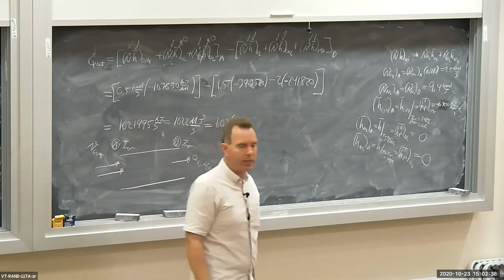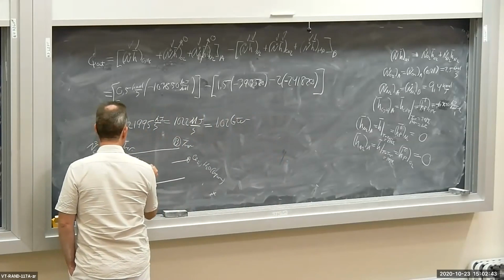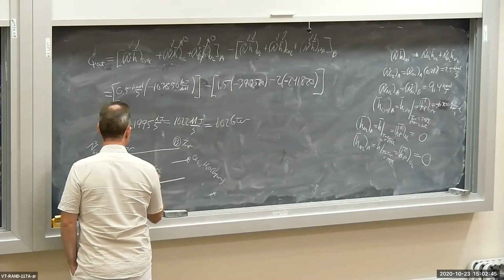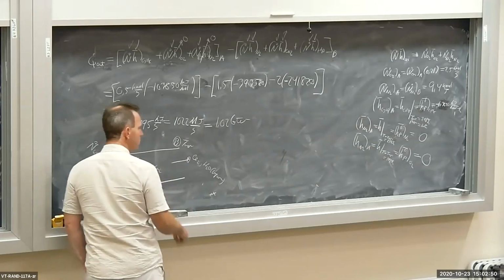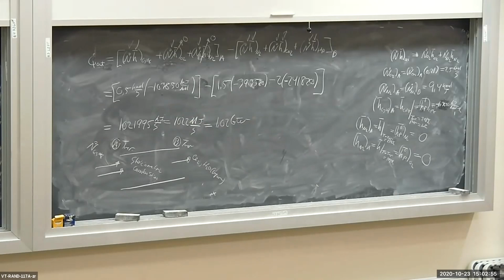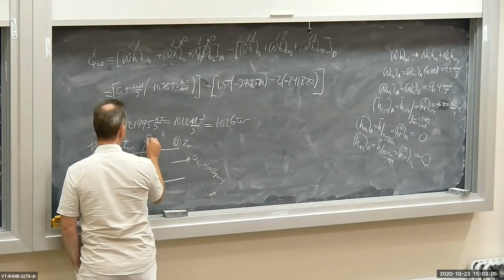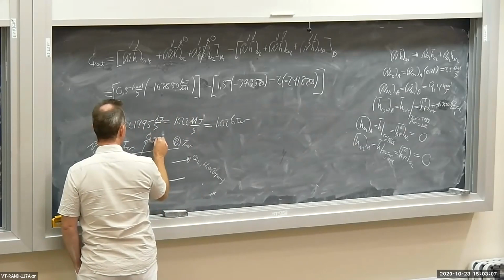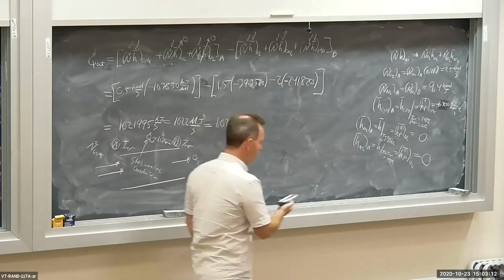It's stoichiometric combustion. Products temperature and reactant temperatures are all at the reference temperature. That's the situation. Let's calculate the heat transfer out. And also I have my Q dot out is 1.02 gigawatts. That's what I've got in the situation here.